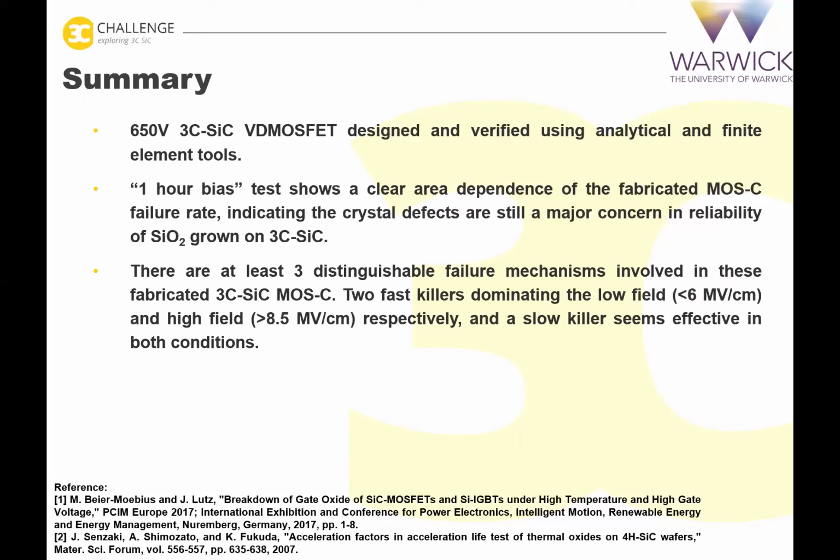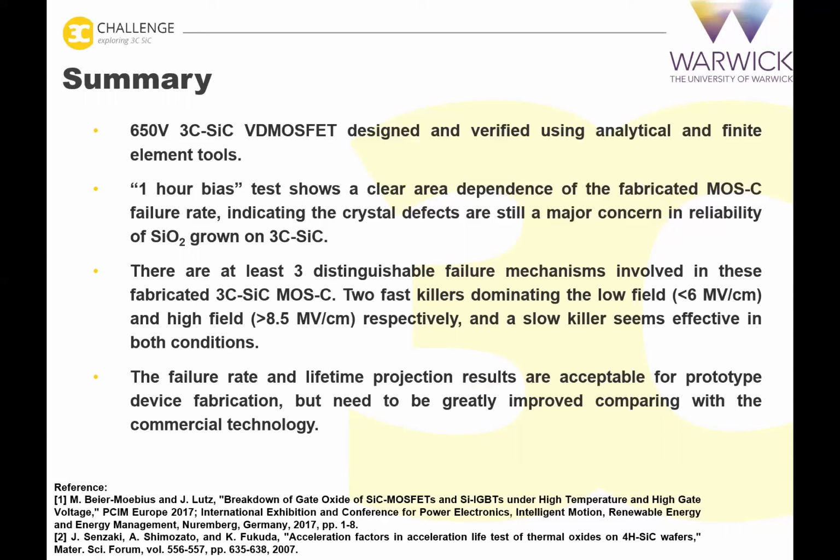And more detailed analysis suggests that there are at least 3 mechanisms leading to the oxide failure. There are 2 fast killers dominating the low and high field respectively. And we have another slower one, which seems to be affecting all conditions. And in the end, the failure rate and lifetime estimation results are okay, actually quite encouraging for prototype devices, but need to be improved for the technology to be commercially available.